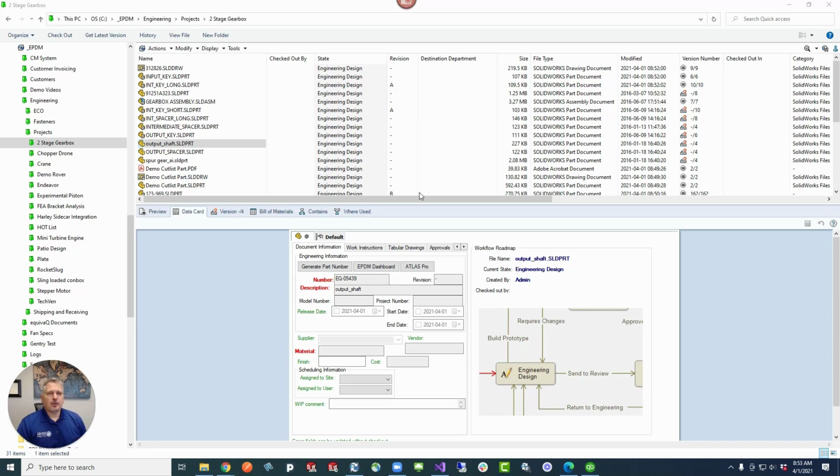One of the things that we've learned as PDM admins is one of the challenges you've run into is finding revisions on drawings, parts, assemblies that are sometimes out of sync, or after they've come back from an edit state, they end up with the wrong rev. Like it went into the edit state at Rev A, but when it comes out of the edit state, it's at Rev G, and we're not really sure what's happened here.